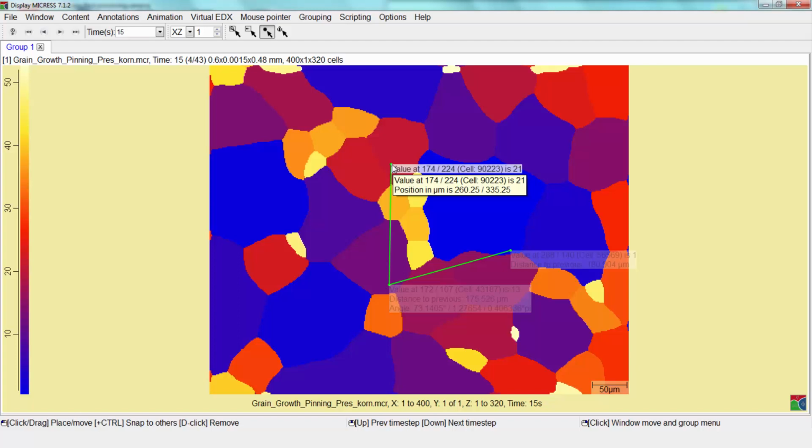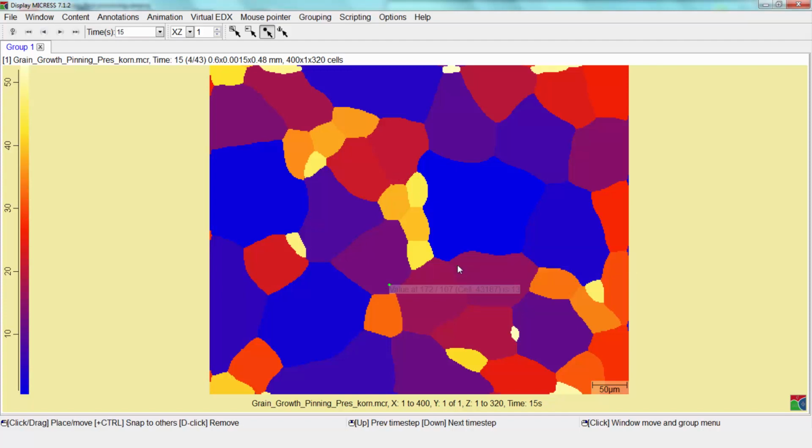and by clicking twice on a certain point it will be removed, and analogously the connected line. A double clicking on a line removes the point-line combination, and when removing a line which lies in the middle between 2 other lines, the 2 related lines at the 2 ends are connected to each other automatically.